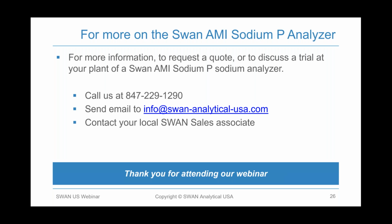Silica, most of the plant companies in this industry in the U.S. monitor the silica. It is not a required monitoring point by EPRI and IOPS, but due to the issues with increased silica and carryover in the steam resulting in deposition on the steam turbine, which impacts the efficiency of the steam turbine.